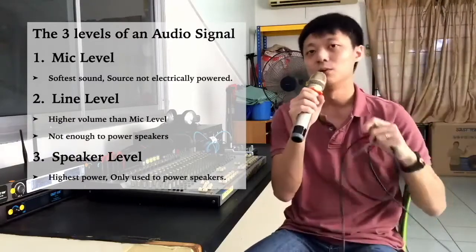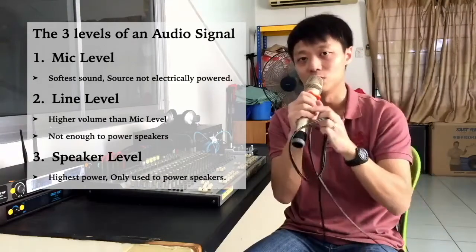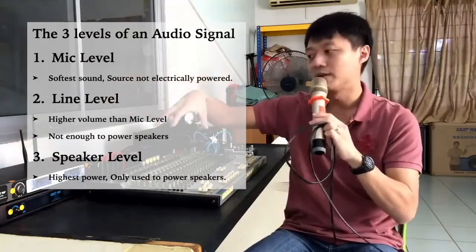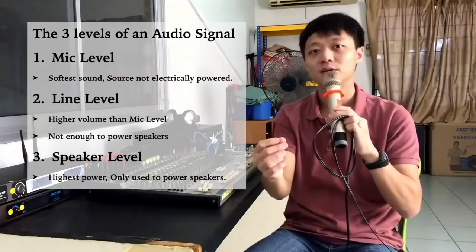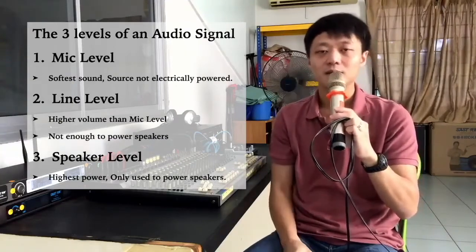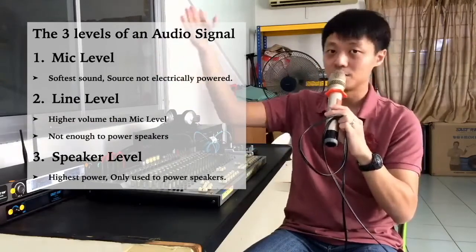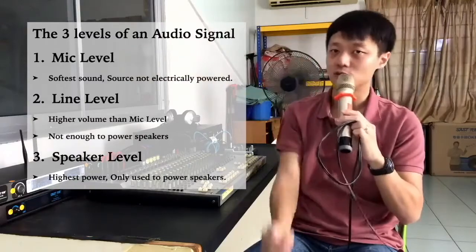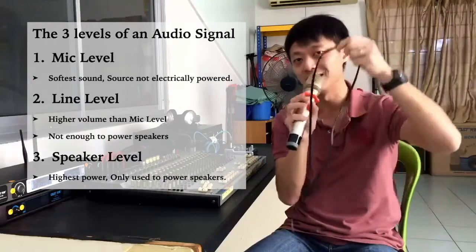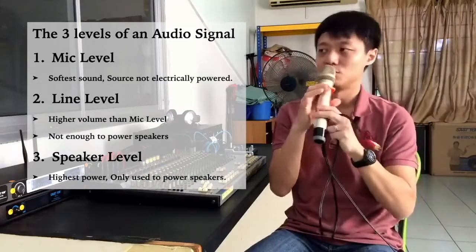The second level, which is slightly higher than the mic level, is called the line level. The line level is used to transfer audio signal from one device to another device. The line level is powerful enough to power a small headset that you're wearing, but it is not powerful enough to power the speakers. The speakers that you see in our church, we have 5 speakers in total, and none of them can be powered by line level signals. Line level signals are carried in this kind of audio cable as well, but they are not used to power up the speakers.